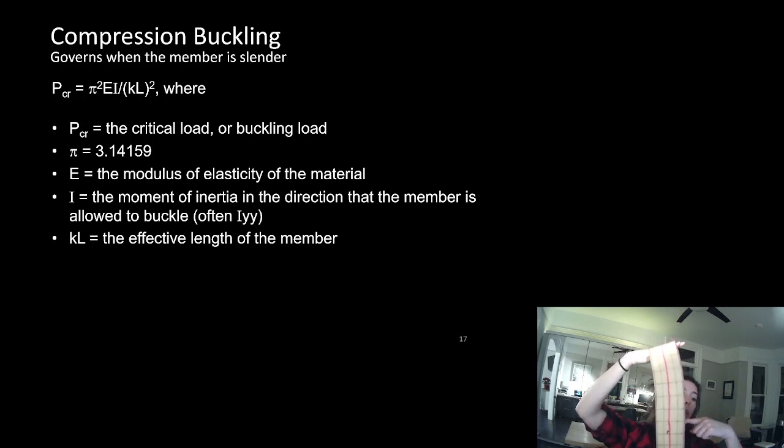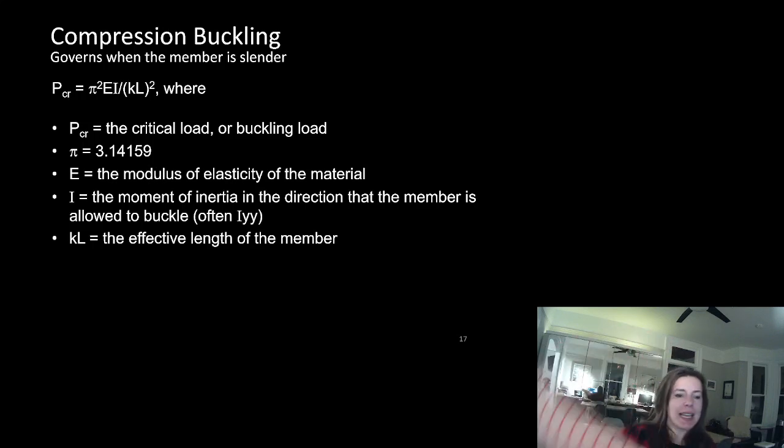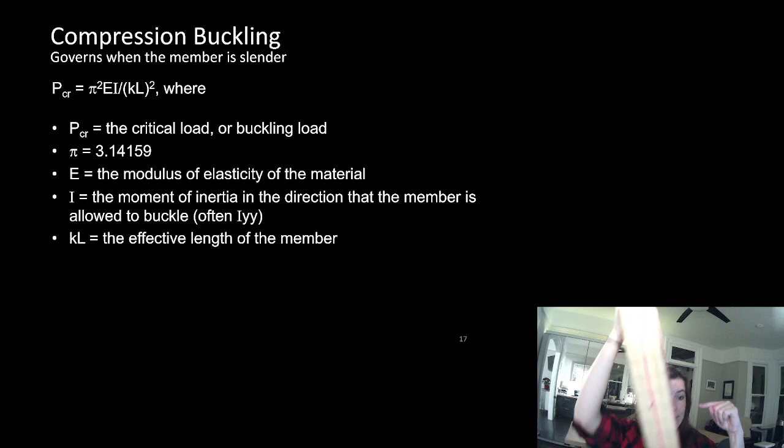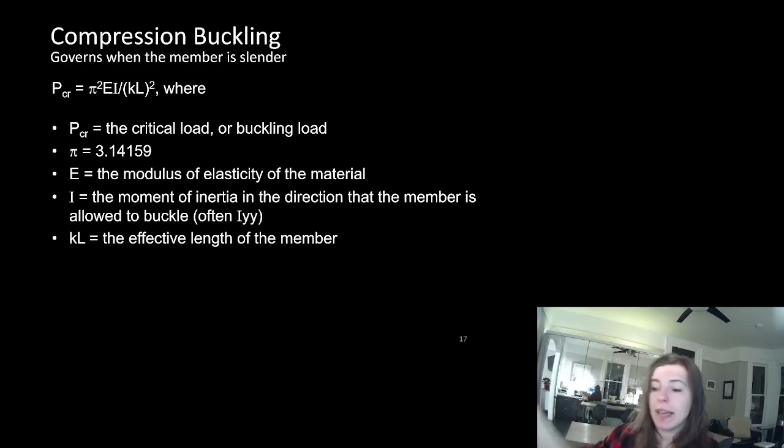I'm pushing way harder than I had before. It's not buckling. It did not take much. The amount of load that I feel going into this finger, stopping it from buckling, is a fraction of what I'm pushing down on. I can tell you statistically it's about 2%, but that's beyond what we need to talk about here. So it doesn't take much to prevent something from buckling.